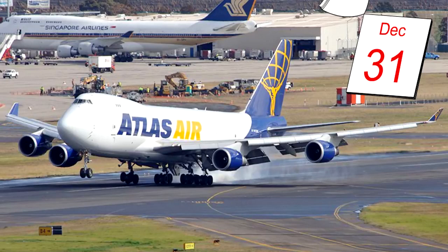All critical components have a safe life, which may be measured in flying hours, landings, pressurization cycles, or even on a calendar basis. After the permitted safe life count has been reached, the relevant item is replaced or overhauled. During the operational life of the aircraft, to minimize the effects of metal fatigue, aircraft designers apply the principles of fail-safe or damage-tolerant construction.